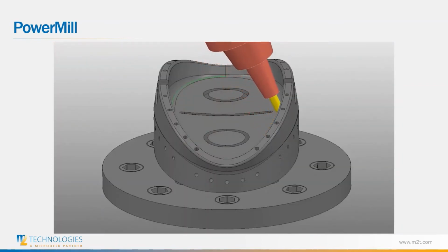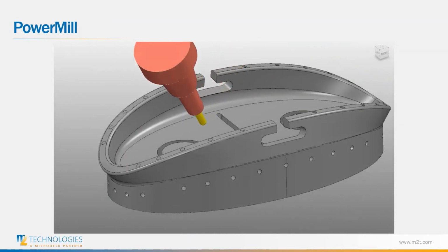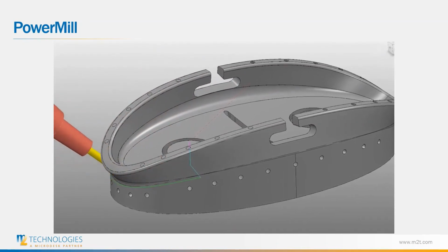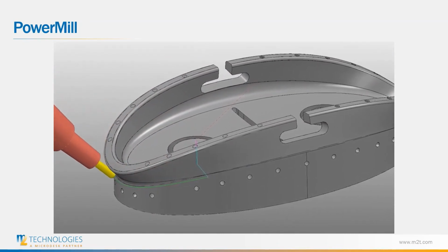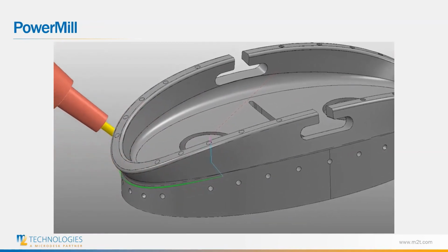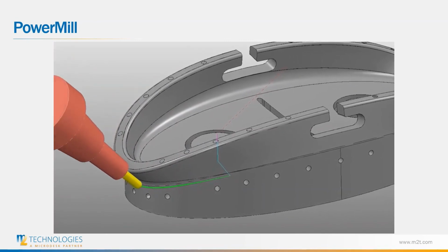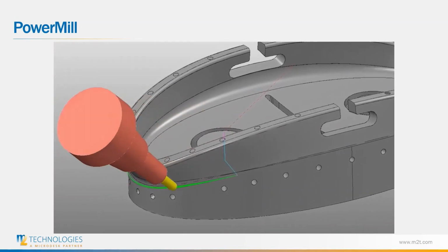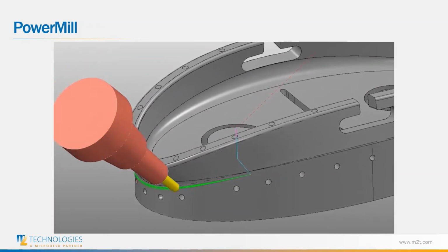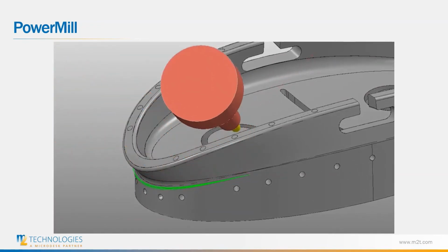Once in 5-axis mode, users can choose from a variety of options to achieve the optimum tool axis motion. Fixed angle toolpaths can machine undercuts and other features by rotating your machine into a position for cutting with the rotary axis locked. For regions of your part that cannot be machined with a fixed orientation, PowerMill offers user-defined points, lines, or curves to control 5-axis motion, allowing features to be machined in one go.